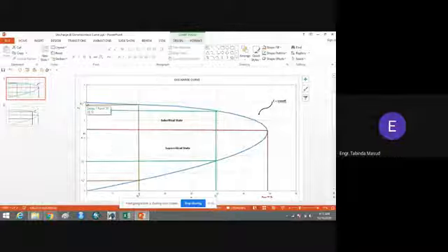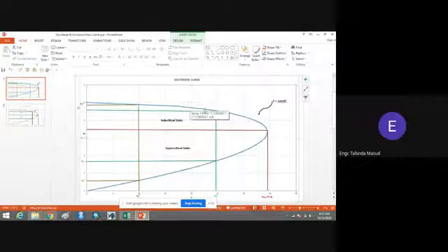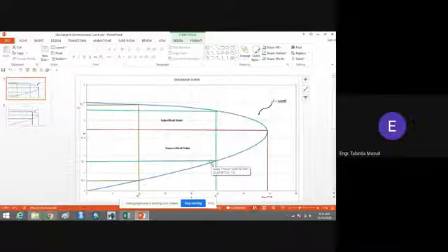Now when you open the gate, what happens? The depth of the flow starts decreasing and the discharge starts to increase. At this point, you get the maximum discharge, and then it flows towards the downstream side, where the depth of the flow continues to decrease, and the discharge also starts to decrease. So we get this type of curve, where we have the maximum discharge at this point.